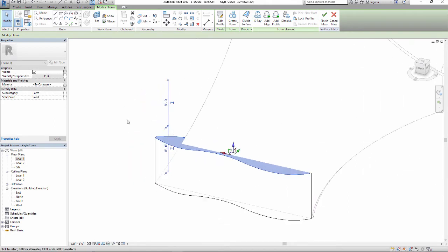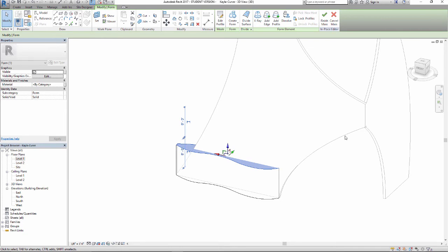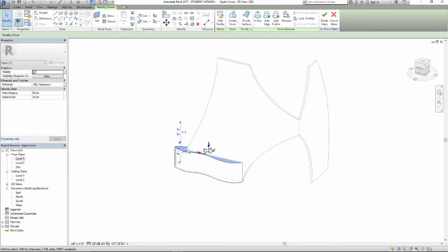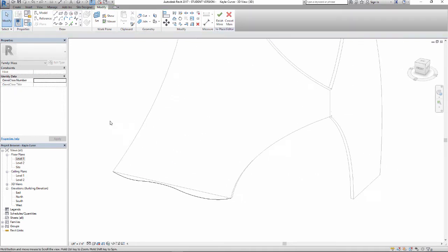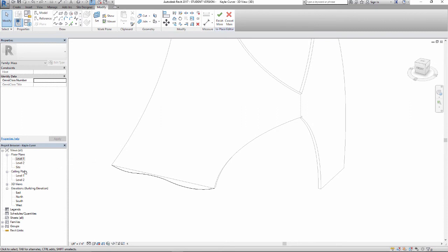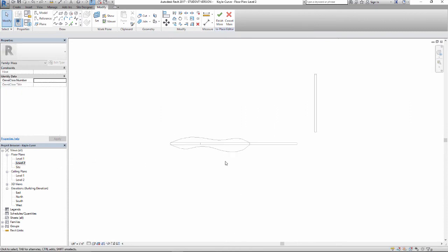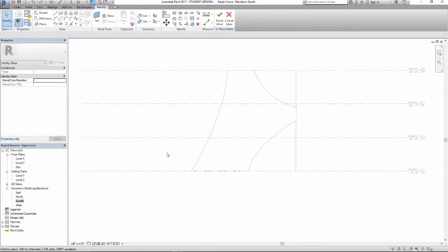That's not exactly what I'm wanting because I'm wanting to vary this extrusion on each edge. So I want to copy this loop and then make some variations with it as it goes up. Now, in theory, with the Loft tool, I can actually go up a level and just draw new curves and then connect those two things together. And in general, that does work. But the more complex that I get, the more reliable of a system I need to build as well. So typically what I like to do is work with this exact same profile over and over and make simple modifications to it. That method for me just seems to be a little bit more reliable.